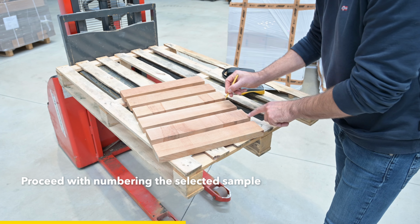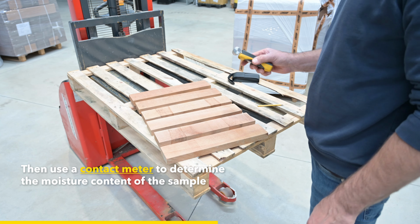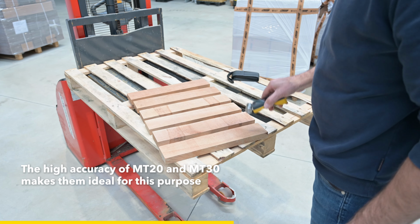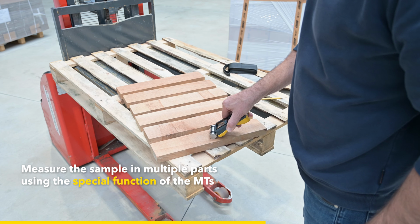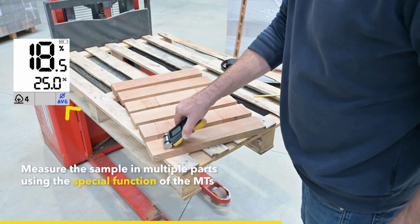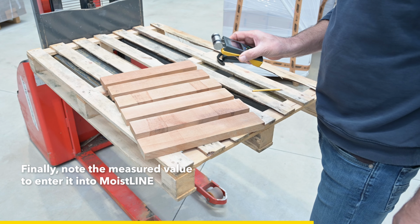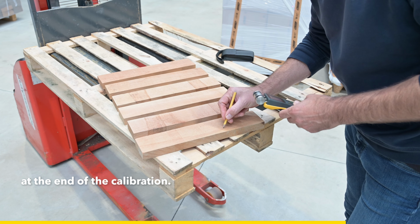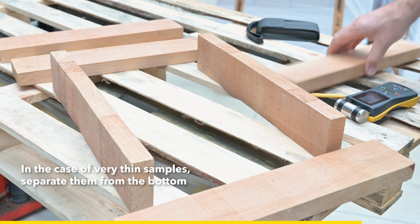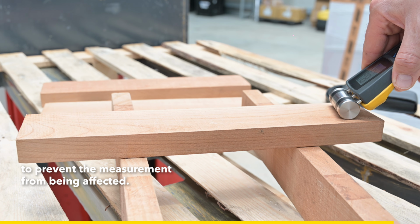Proceed with numbering the selected sample. Then use a contact meter to determine the moisture content of the sample. The high accuracy of MT20 and MT30 makes them ideal for this purpose. Measure the sample in multiple parts, using the special function of the MTs to determine the average moisture content. Finally, note the measured value to enter it into MoistLINE at the end of the calibration. In the case of very thin samples, separate them from the bottom to prevent the measurement from being affected.